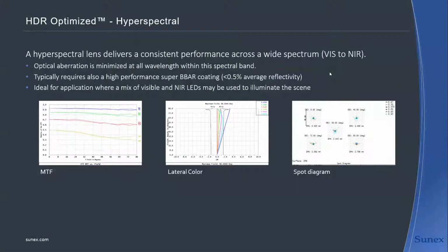So you've got all this light from across the band that you're trying to, first and foremost, image properly where you want it to go. On top of that, the other materials in the lens react differently to different wavelengths. You can think about anodize as a good example. Something that might look completely black in the visible may have 20 or 30% reflection in the near infrared. So it's not only a problem of managing much more light, but light of different nature almost.